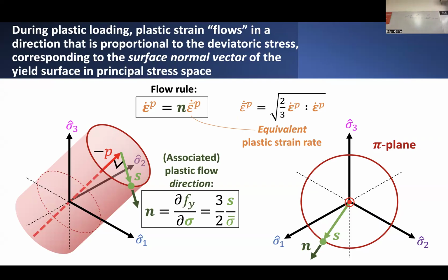to define the apparent rate at which plastic strain occurs, and more specifically, not just defining the rate at which plastic strain occurs, we also have to define how exactly the plastic strain is evolving. In the one-dimensional case, we had to resolve if we were stretching the material this way, was the plastic strain increasing or was it decreasing under compressive loading? We had to distinguish, in other words, what's the apparent direction in which plastic strain will start to flow or